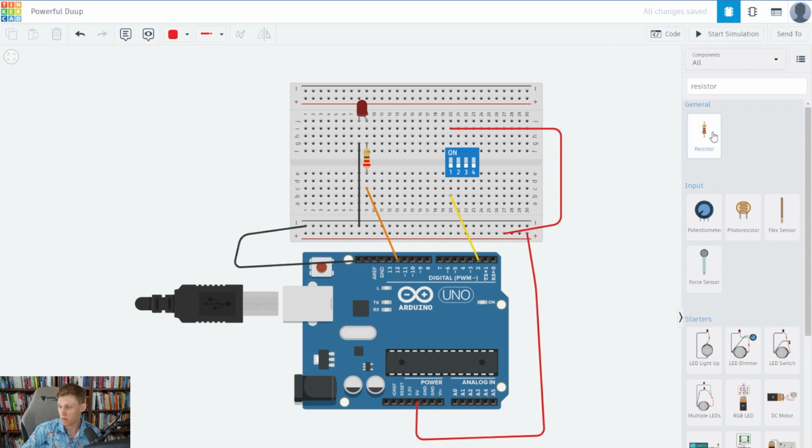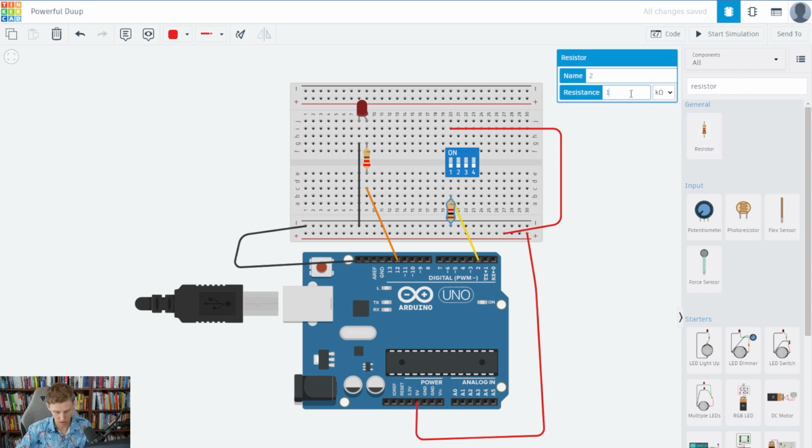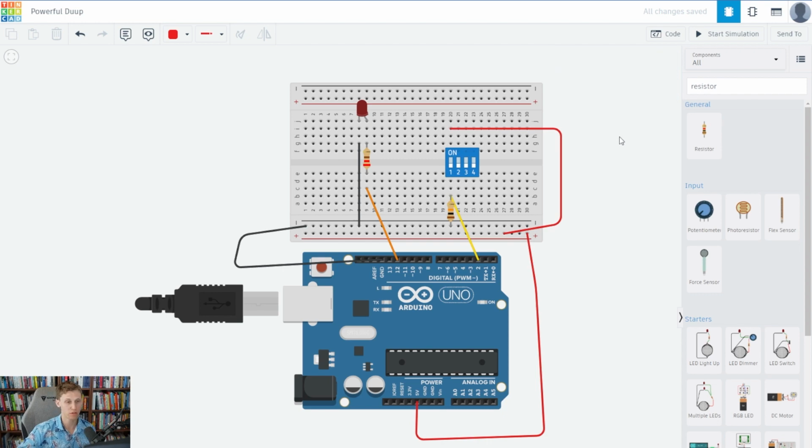So yes, a pull down resistor is quite literally a resistor, and in our case, we're going to be using a value of 10K ohms. And this quite literally just sets it to ground. So this is so we give our circuit a reference value of where ground is, so that anything above that, 5 volts up, is considered high. And with this, we should have a completed circuit.